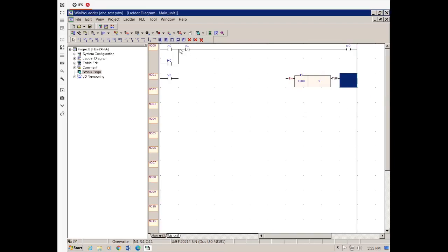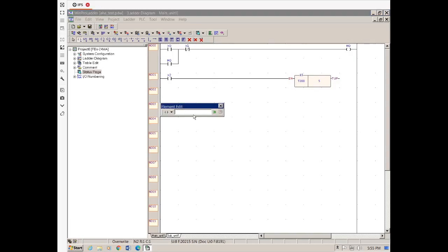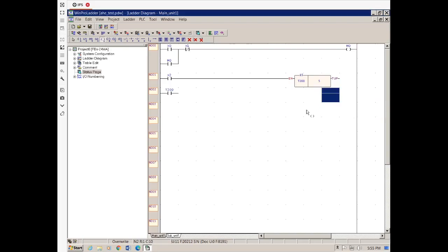Once that is done, you can again draw the lines as usual and connect them. Here for drawing, you don't have a shortcut as of yet, just to get the output. To get the timer value, you can say the address of the timer, which is timer 200, then put it into a memory output state, let's say y0. In this manner, I think there is a shortcut, so you can click on H. So yeah, you can just draw and complete the line.